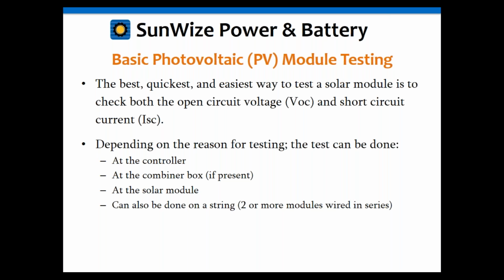We're going to focus right now just on the VOC test because 75 to 80% of what you need to know you can learn from that, but there are some things you can learn from the ISC test, and we're going to go ahead and table some of that for our next webinar with regards to system troubleshooting.